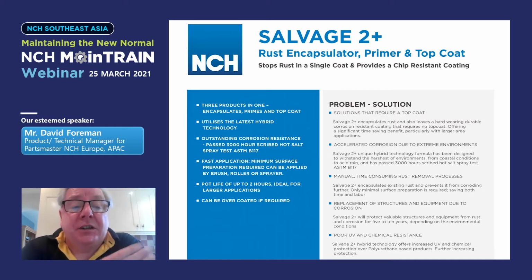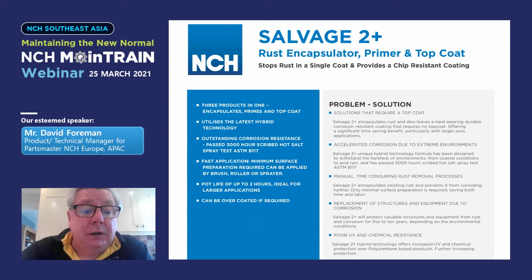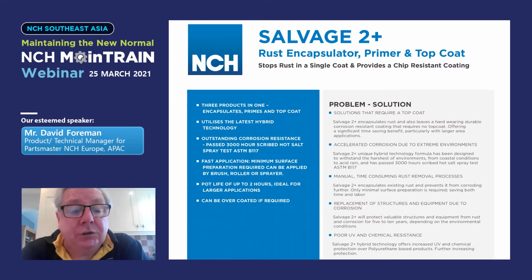As I've said, it utilizes the latest hybrid technology. You've got outstanding resistance to corrosion, the salt spray test. Very fast application time, minimum surface prep. All you need to do is to remove any loose corrosion. Basically, it has a pot life of about 2 hours, so it's ideal for larger applications. And it can be overcoated if required.